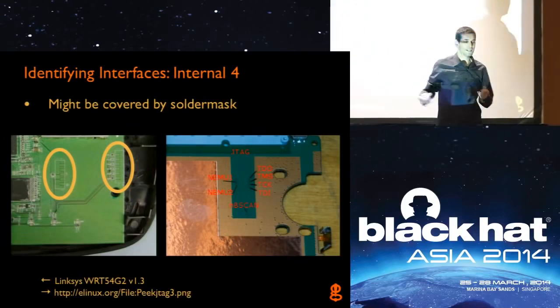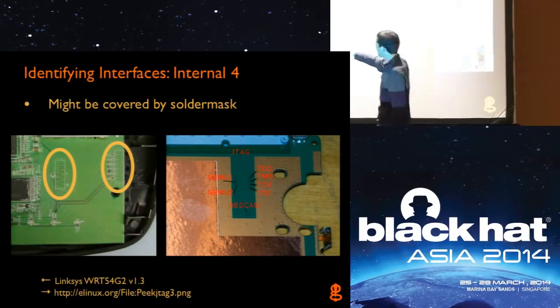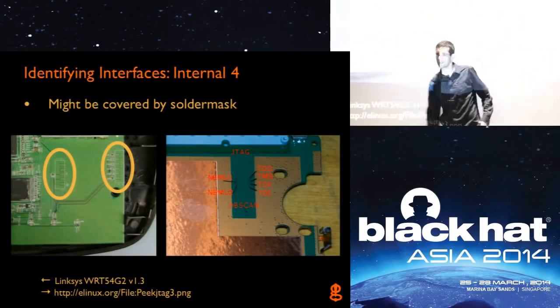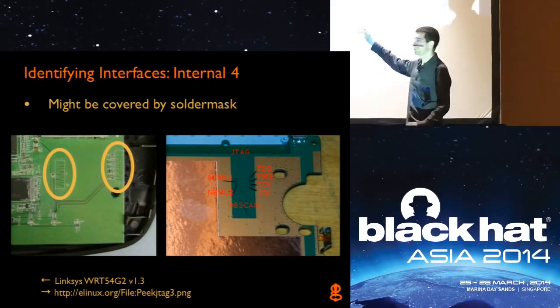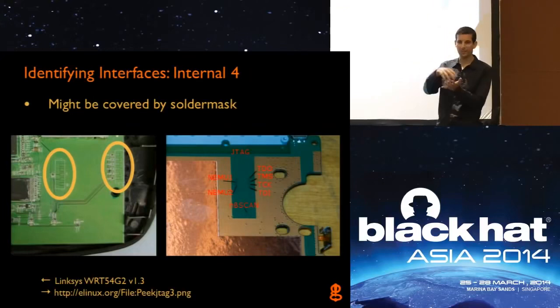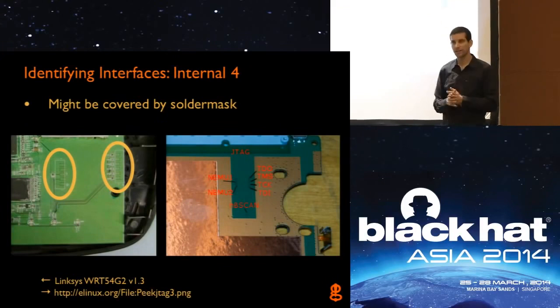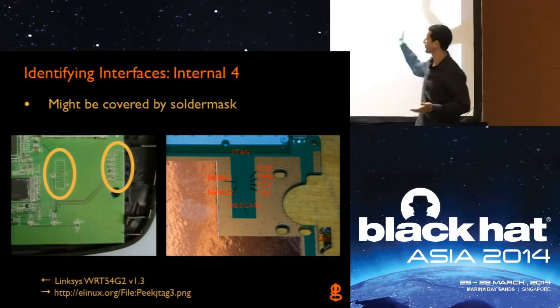The only way you can get access to the actual copper and make contact is to scrape off the solder mask. It seems like maybe during manufacturing, or during development, that area was exposed, so developers could have some connector plugged in, and then they just changed the solder mask plot when they were manufacturing their boards to cover that over.